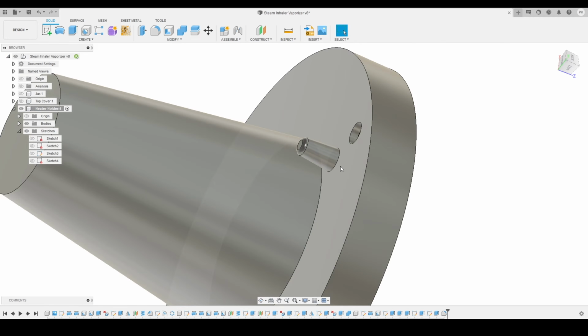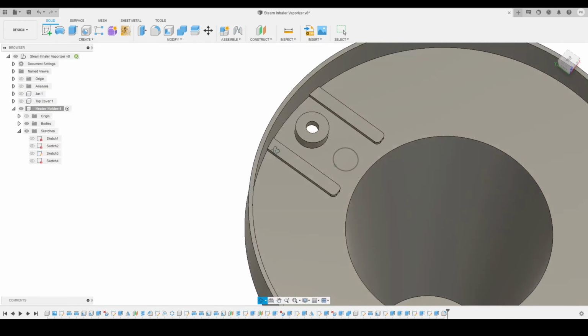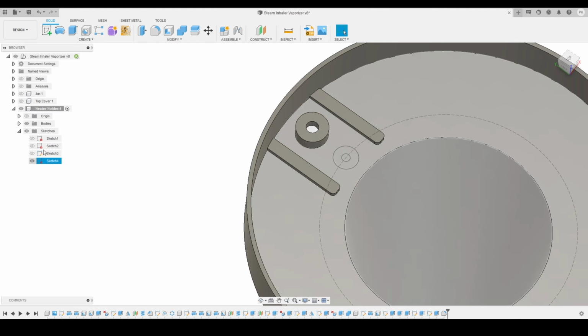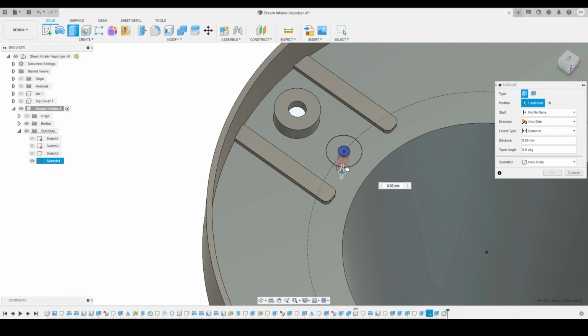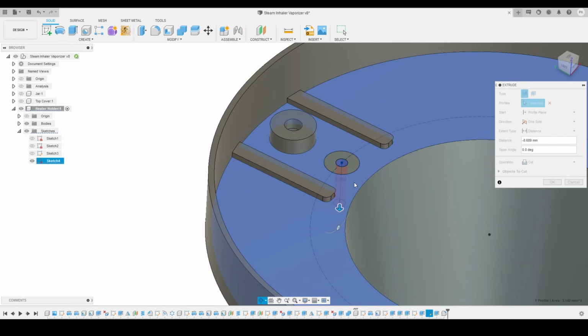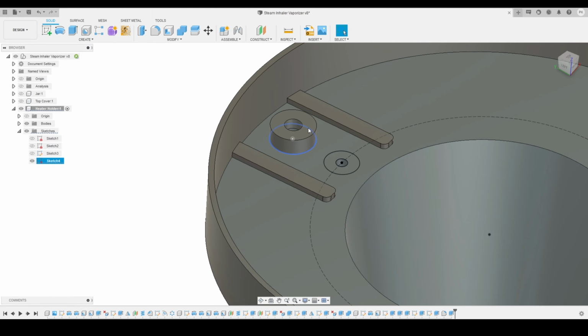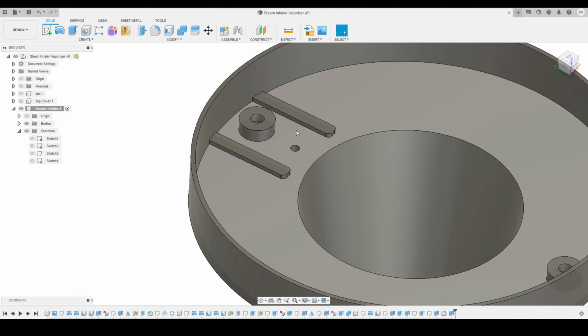Here you can see that. So this is what we had created. Now again I will turn on our sketch and activate the extrude tool, and this time I'm going to create a hole like this. Since the total length was 10 millimeters, I will just create a hole up to -6 millimeter and press OK. So guys, here is a small problem, so I think I have to edit my sketch again.